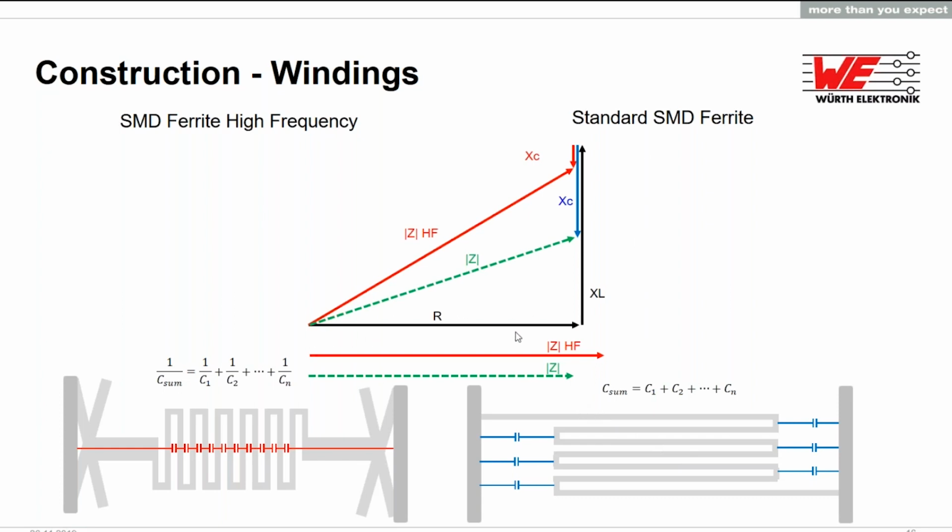As we can see from this vector diagram, when you have less capacitance, you have a smaller decrease in the imaginary part. And with more capacitance, obviously lower. So when we take the magnitude of the impedance, your Z would be higher when you have smaller capacitors.